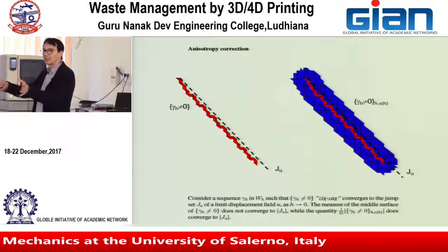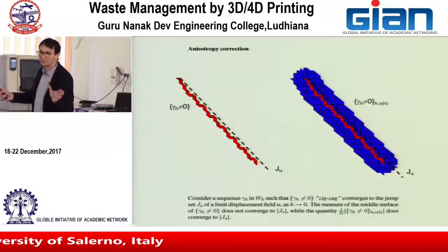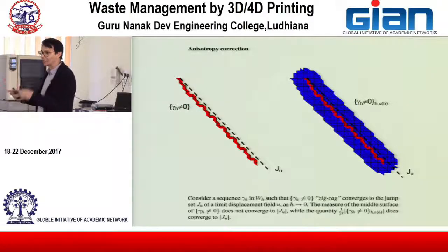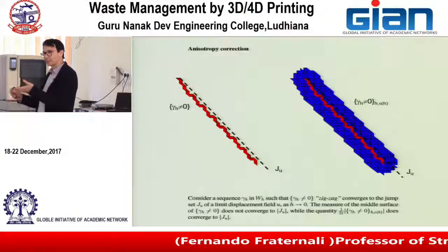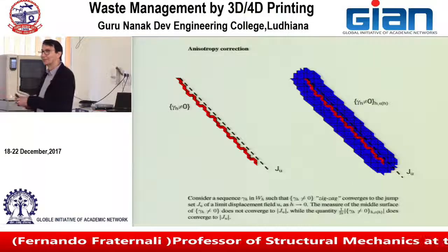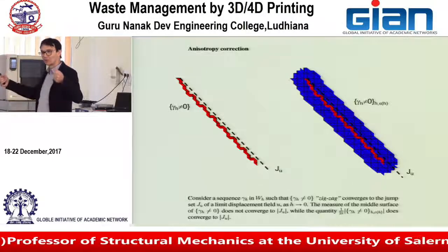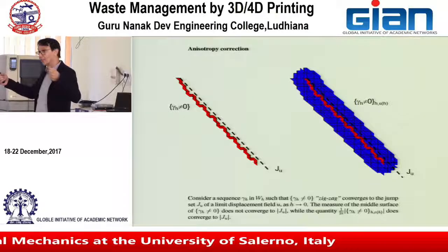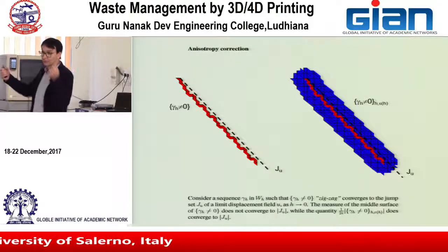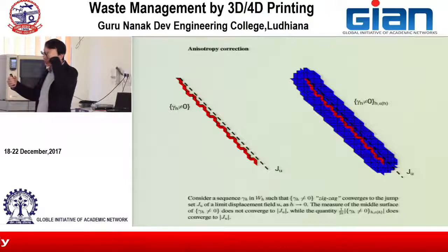You set the elastic moduli to 0. This is simple. To remove an element, you don't even need to remove it. You set the material properties of that element to 0, and you recompute the solution through the finite element code. You will get a different solution from the one with the element in place.